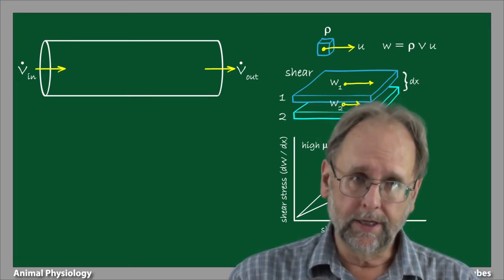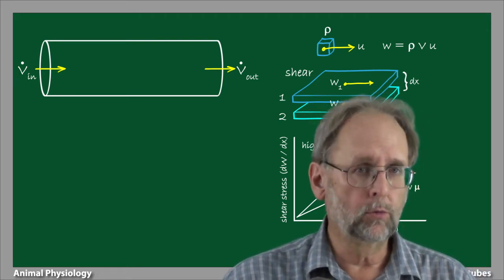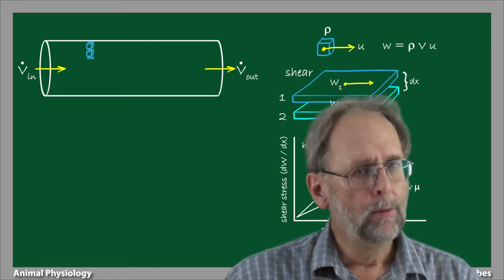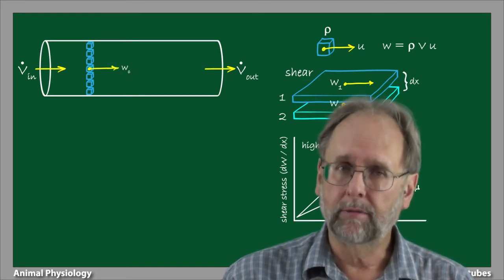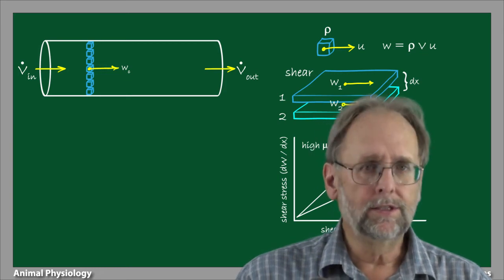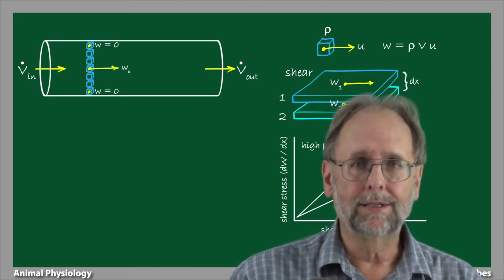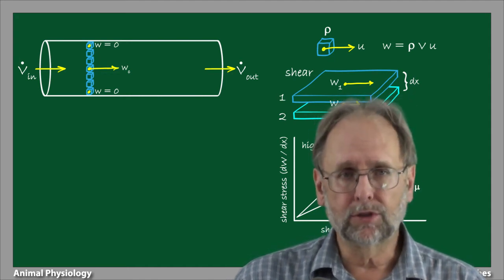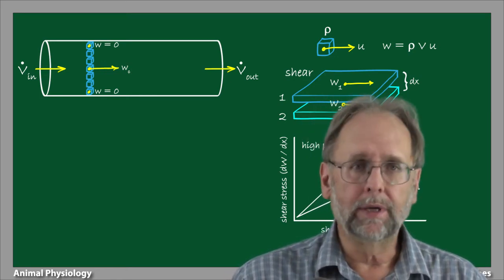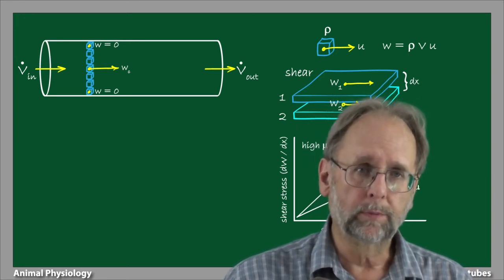Volume flow of blood through a tube imparts a certain momentum to the fluid, but confining the flow in a pipe necessarily involves the transfer of momentum from the flowing fluid to the stationary tube wall. This is where the viscosity of the fluid becomes significant. Parcels of blood in the center of the tube have a particular velocity and therefore a particular momentum. At the inside surface of the tube, in contrast, the fluid's momentum is zero because it is adhered to the immobile inside surface of the tube. This is known as the no-slip condition, and it means there will necessarily be a transfer of momentum from the flowing blood to the tube.